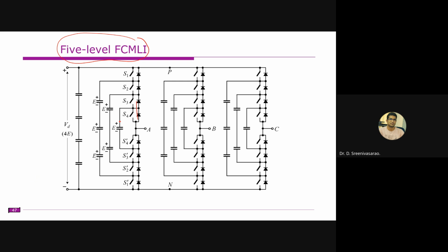For that, what we normally do is that the stored energy moves to the crankshaft. From the crankshaft, it moves to the engine or the motor. From the motor, it moves to the inverter. From the inverter, it moves to the grid side, or to some supercapacitors or some energy storage system. Sometimes it will feed to the grid, or sometimes it serves internal purposes like turning on lights, or charging the inside batteries of the train. Most of the time it is used to serve these local loads inside the train instead of feeding to the grid.